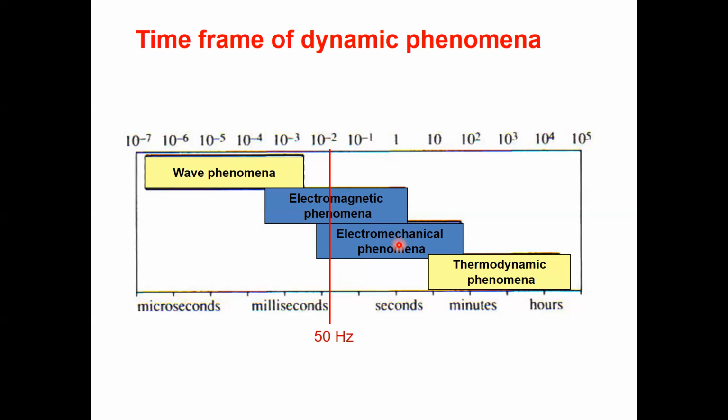It has a wide range, because you have inter-area oscillations and even local oscillations. In most cases, low frequency oscillations can persist for a longer duration even after the disturbance. If the rotor angle oscillation is poorly damped, the oscillation will last for several seconds, maybe up to 1 minute, or it may persist throughout. That is also possible.